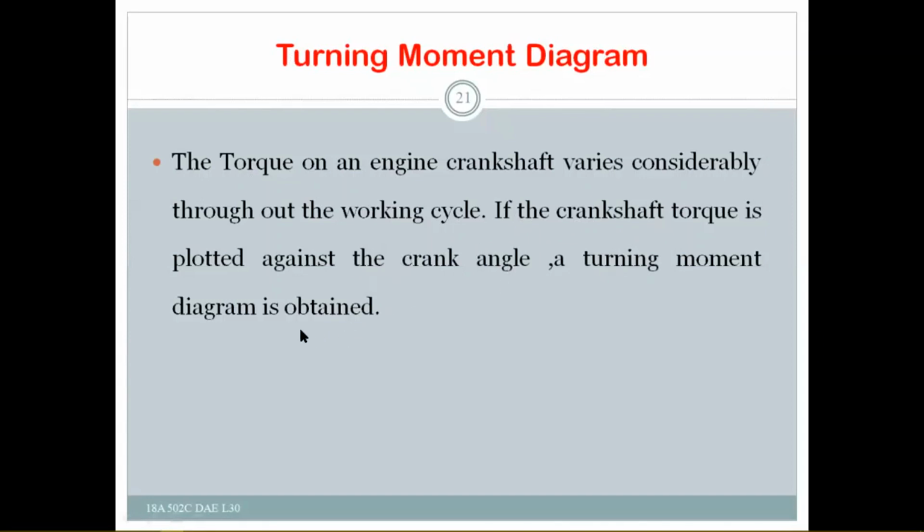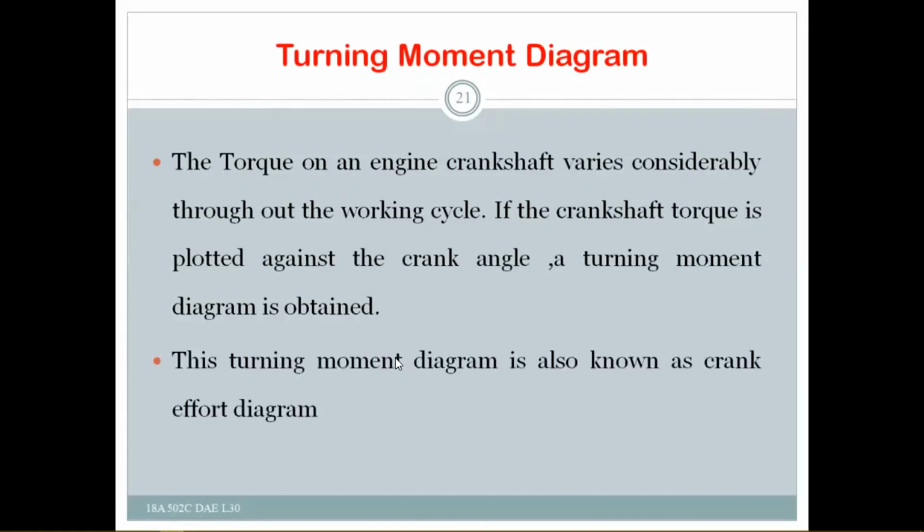That means simply we can define this as the diagram between the crankshaft torque and the crank angle, which shows the variation of crankshaft torque against the crank angle, right? So this is the turning moment diagram.